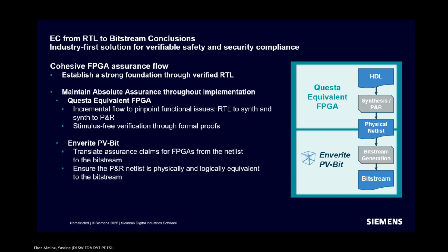At the block level, they check that the synthesis doesn't break any functionality, especially if they're inserting things like power optimizations or safety mechanisms. They don't have to wait until the top level. So yes, there is support for partitioning, both automatic and manual, using hierarchical information.